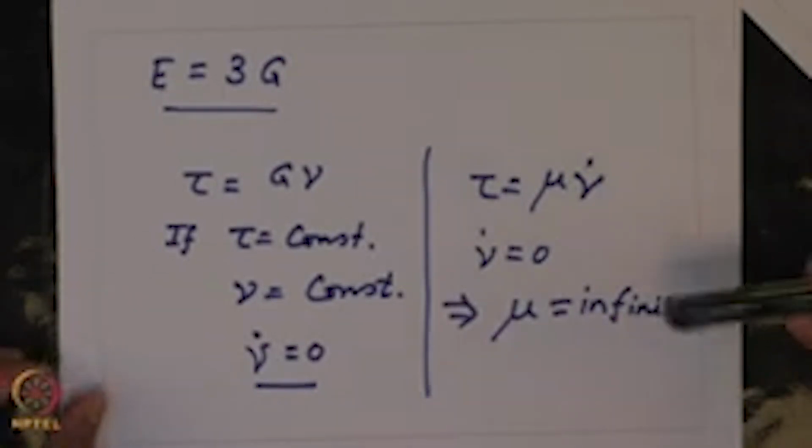And this is the reason why when we do viscosity measurements, or probe the rheology of systems under constant shear, it is not of relevance, because if the material is elastic, this is infinite. Secondly, if you have fragile materials like ECM networks, if you expose them to constant shear, they will actually fall apart. Then the point of actually characterizing their physical properties no more exists. For this reason, what is ideal is to use oscillatory measurements.